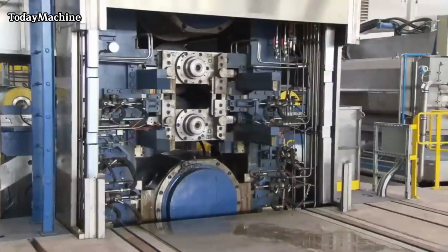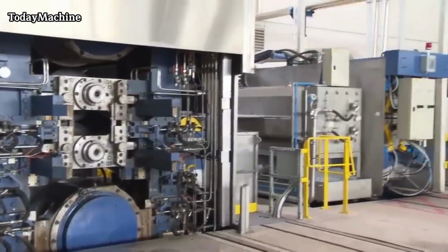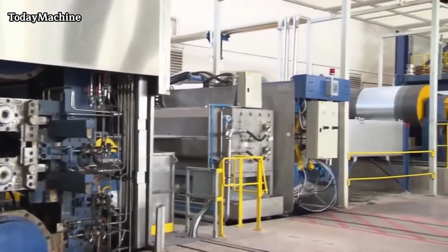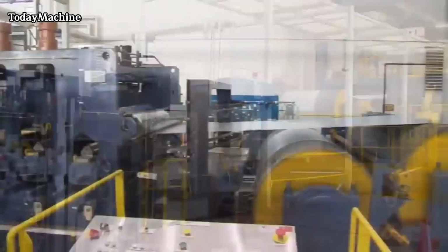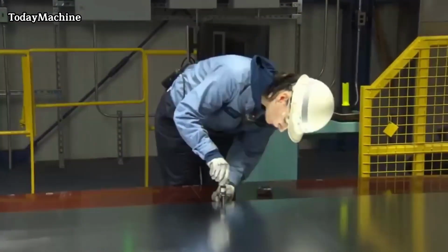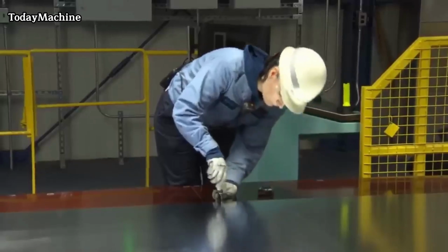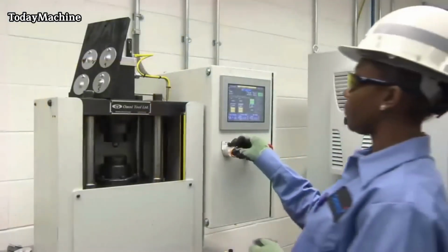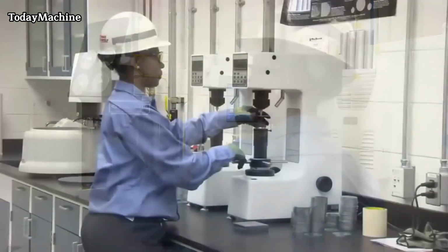As the steel enters the zinc bath, the molten zinc reacts with the iron in the steel surface to form a metallurgical bond. This bond creates a protective layer of zinc-iron alloy known as the galvanized coating on the steel. The thickness of the coating is determined by the speed at which the steel is pulled through the bath and the amount of zinc present in the bath.